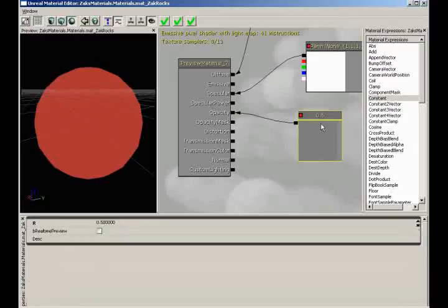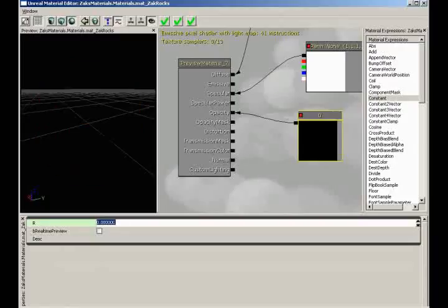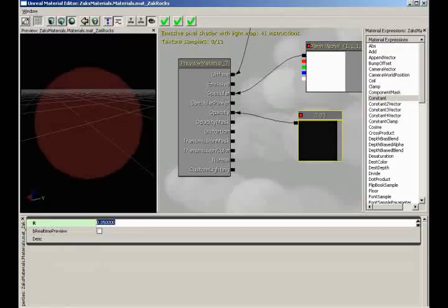Now, the reason you're going to use that is because when you're using the translucent blend mode, you can start using these various levels. So if I set this to 1, we get completely opaque. If I set it to 0, we get completely transparent. I can set it to like 0.01, and you can just barely see it. In fact, on the video, it might not even show up at all. So let's say 0.03 or 0.05, and you just really start to bring that up slowly but surely. But do keep in mind that you don't have that default lighting anymore. So you would have to fake that.